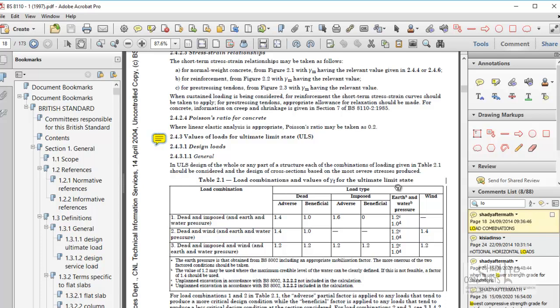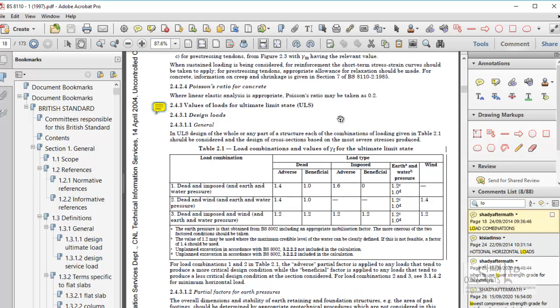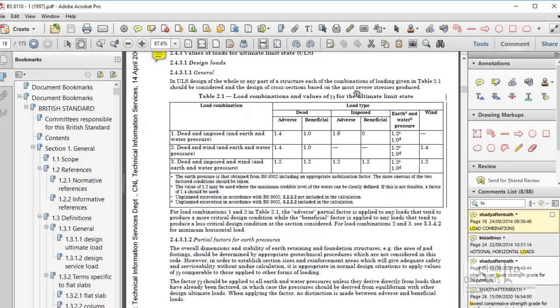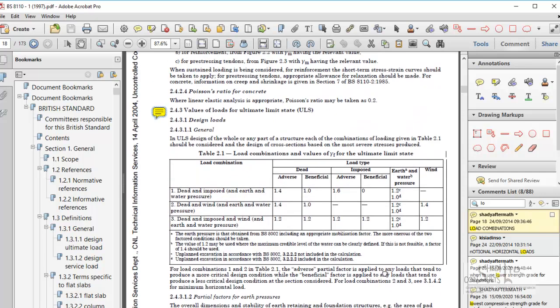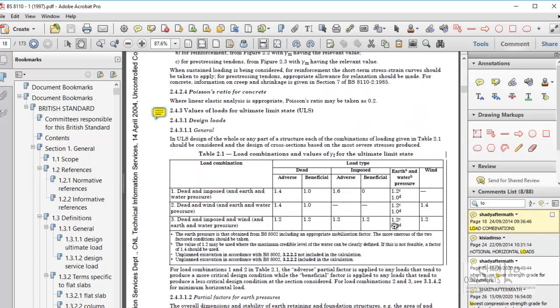Ultimate limit state considerations are considerations that cater against flexural failure, shear failure, fatigue, deformation of the structure, and so on. Partial factors of safety are applied to the characteristic loads, and these loads provide design bending moments, design shear forces, and design torsional and axial forces, which are used to design the structural element against design shear stresses, design bending moment resistances, and so on.